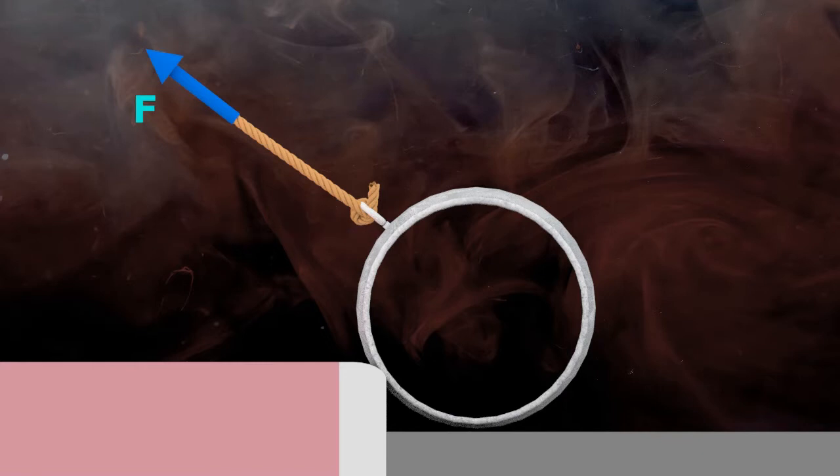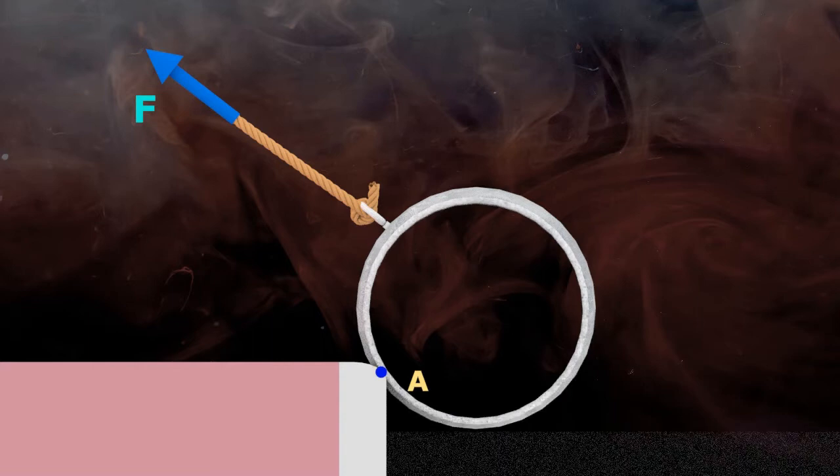Second type of force is support reactions. Support reaction acts whenever an object is in direct contact to other bodies. In our case, pipe has point of contact A with the edge of curb. So if only curb is considered and if any free movement of pipe is restricted due to the curb, reaction of same magnitude but in opposite direction will be developed at this point A.